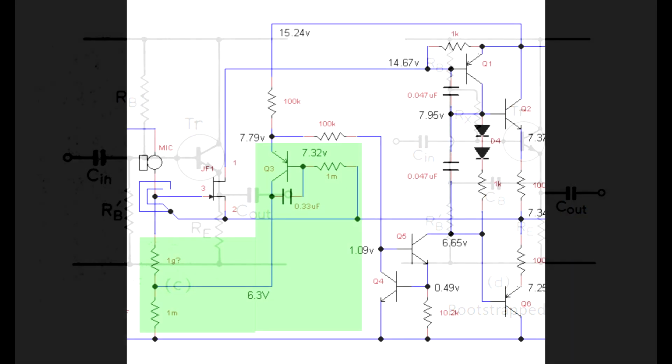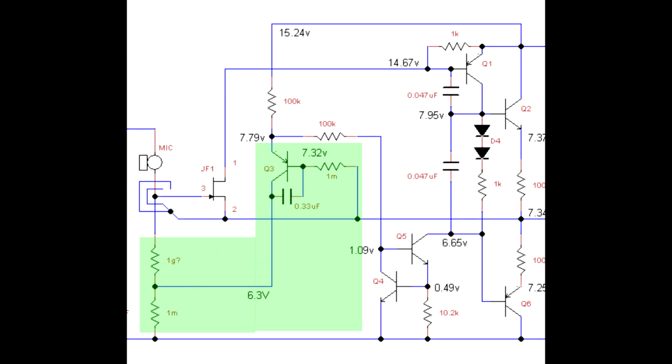So in our circuit, I think you can see the bootstrap now. There's a transistor that buffers the signal, but the base of the transistor is monitoring the output. That center line through the circuit is the output signal from the push-pull amplifier at the end.